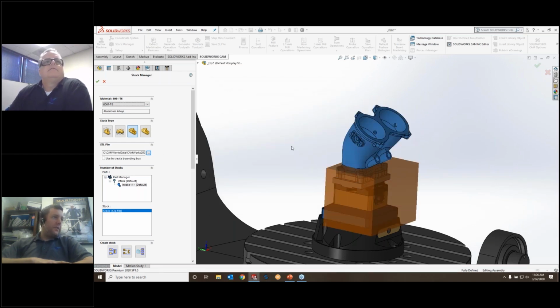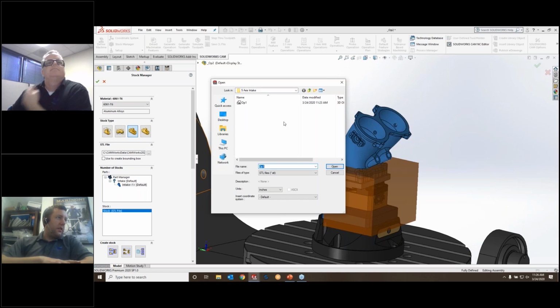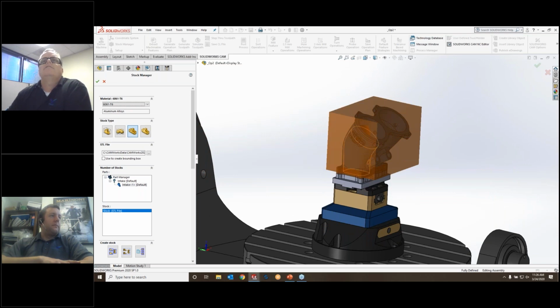Oh, looks like you forgot the coordinate system there, Tim. How did that work? So just click back on the box again. Okay. Go back in to open the STL file. Right here? Yep, right there. Click on the op, and then change the coordinate system down here at the bottom to part coordinate, and you should be set. Okay, part coordinate. It opened. Oh, gotcha. Okay. SolidWorks trick. See, I'm just a cam guy, man.